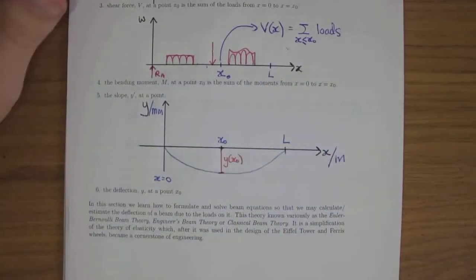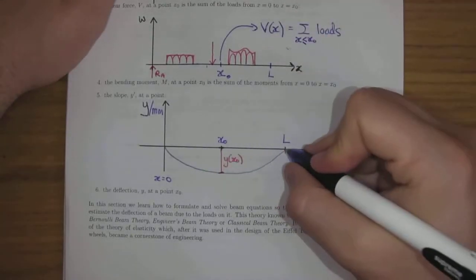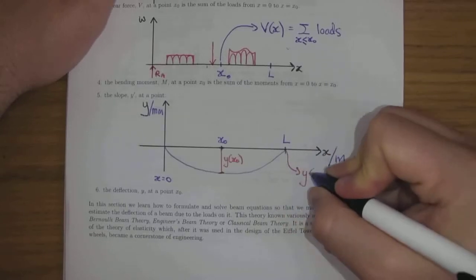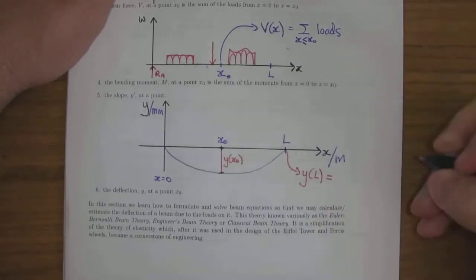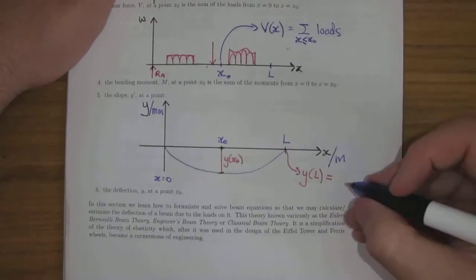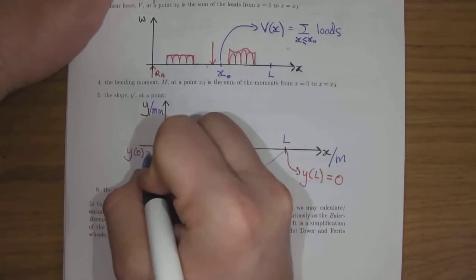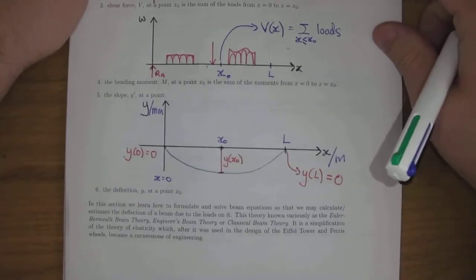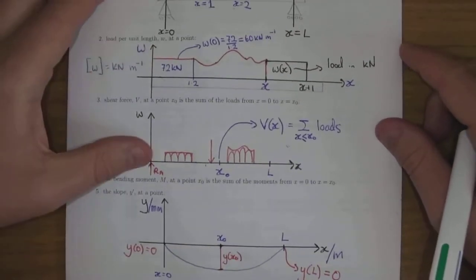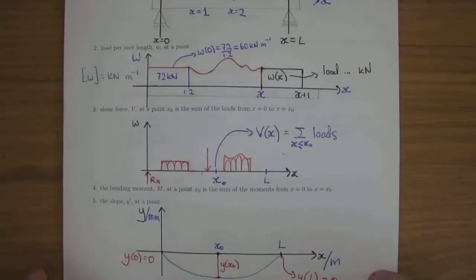And you have to understand that for simply supported or fixed ends, and we might do some of these up here, the deflection at the span, if it's fixed over here or supported at all, well, the distance between the neutral and where the beam actually is, is 0. And a similar story over here, the deflection at 0 is also equal to 0. Okay, is there anything we can do here? If there's no point load here, we can say that the shear at 0 is RA. That's something we could write. And here there's nothing of much interest.